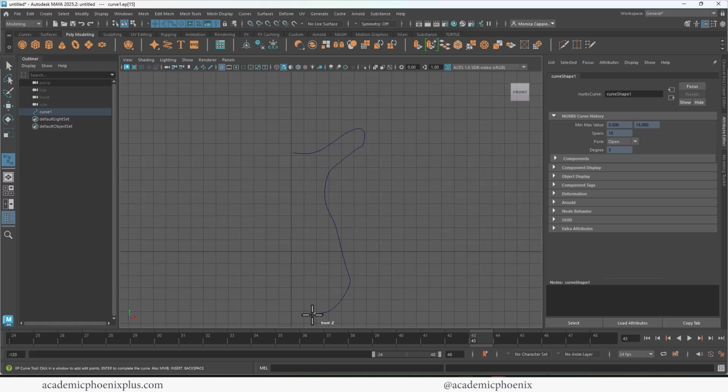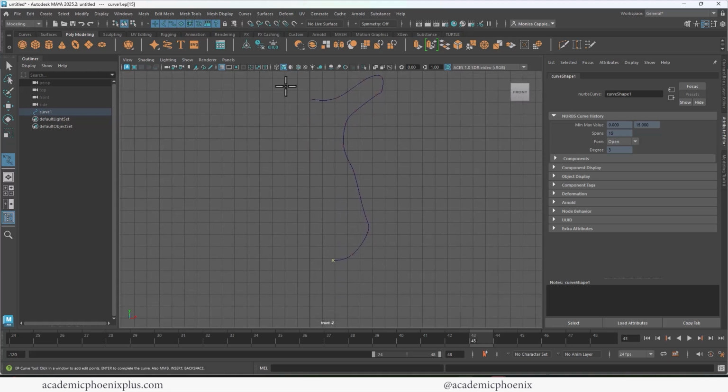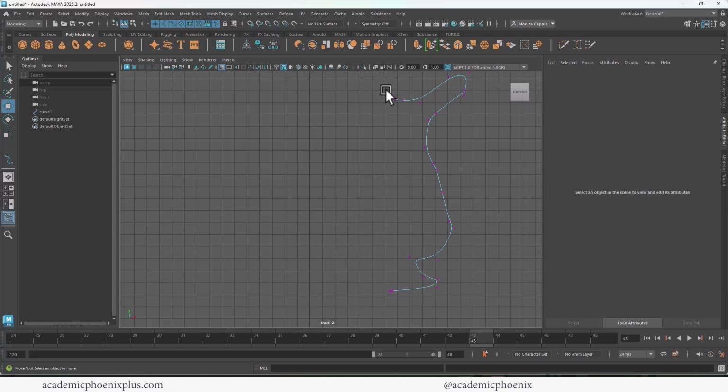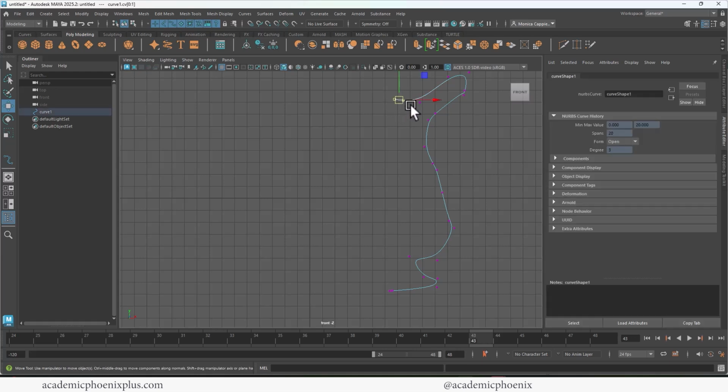Now you'll notice that I am working on the origin right here because my pivot point is going to end up right there. So I'm going to hit enter. And if I press W, you can see that the pivot point is exactly where I want it to be, which is at the center of the object. Now it's not a big deal. If you moved it over here, you can always click on the letter D and place it at the edge of your silhouette. Now I can go to right click, control vertices, and make my changes.